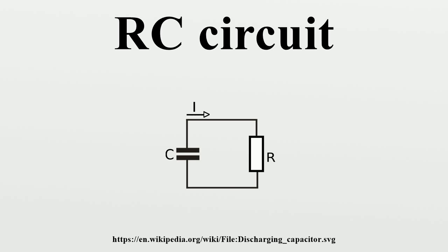The point at which the filter attenuates the signal to half its unfiltered power is termed its cutoff frequency. This requires that the gain of the circuit be reduced to 1/√2. Solving the above equation yields the cutoff frequency, which is the frequency that the filter will attenuate to half its original power. Clearly, the phases also depend on frequency, although this effect is less interesting generally than the gain variations.